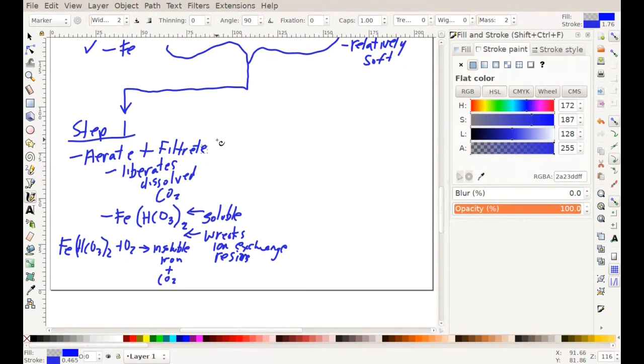Well, back in Manitoba, where I'm from, outside of Winnipeg, if you had well water, you had a lot of iron in it. And it was also hard water, so what we wanted to do was run it through a sodium zeolite softener. But before you ran it through a sodium zeolite softener, we had these things called Patterson iron filters.